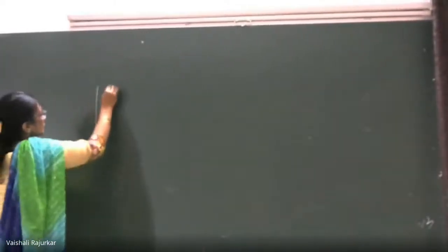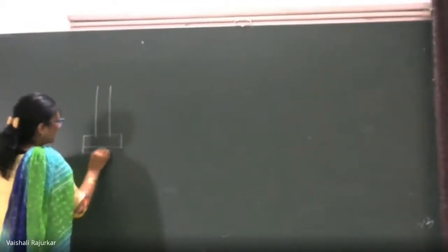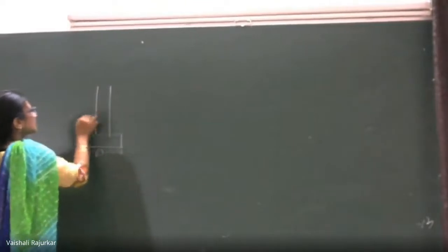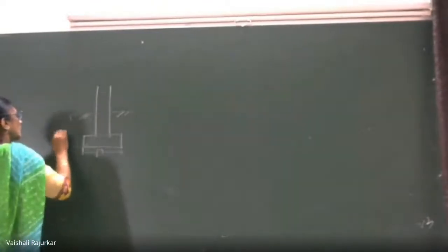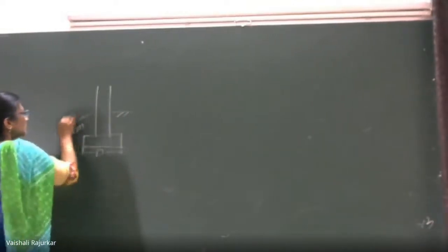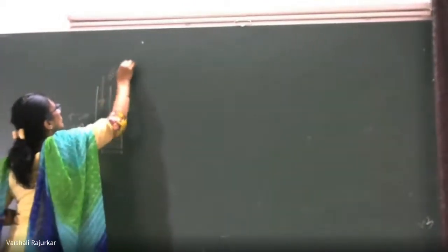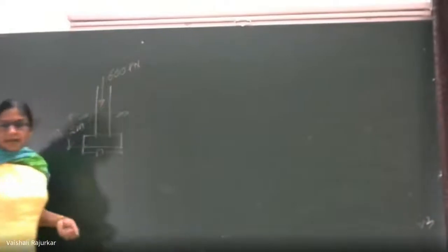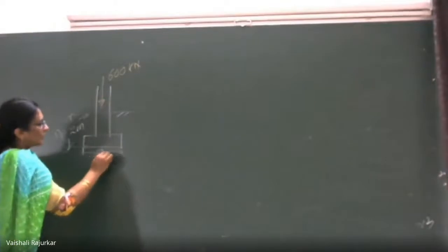Now, this is the circular footing. The circular footing having the diameter D, whereas the depth DF is given as 2 meters. This column is subjected to load of 600 kilonewton. And in this case, load आने वाला जो है that is fixed, and in that case you have to find out the diameter of a circular footing.